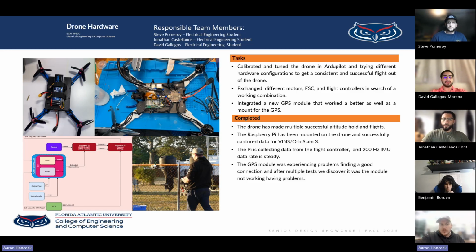One other thing I want to add as well is we made a switch. This does speak solely about the hardware, but in terms of switching out flight controllers, we did play around with the firmware. We made a swap between Betaflight and ArduPilot. The ultimate focus of the project was to configure ArduPilot for autonomous missions. However, we wanted to make sure that the system could fly, so we went with an easier alternative with Betaflight to get the drone off the ground initially. So that is one aspect that we explored.